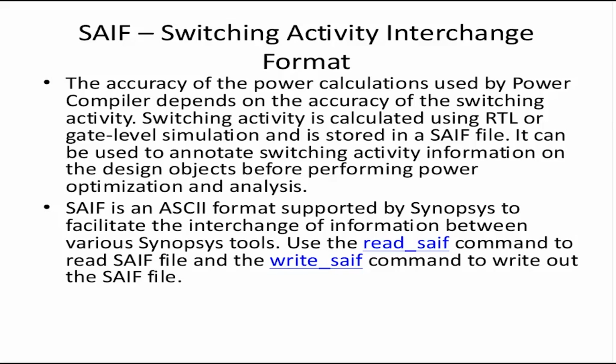SAIF is an ASCII format supported by Synopsys to facilitate the interchange of information between various Synopsys tools. We can use the command read SAIF to read the SAIF file. We can also use the command write SAIF. Write SAIF is obviously not used when you generate SAIF from simulation data, because then you have to read it in. The write is used for some other purpose. It's used when we use some estimates, and we can write out those estimates using write SAIF.